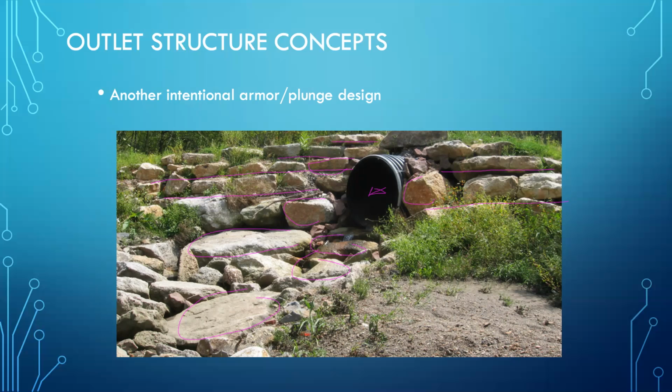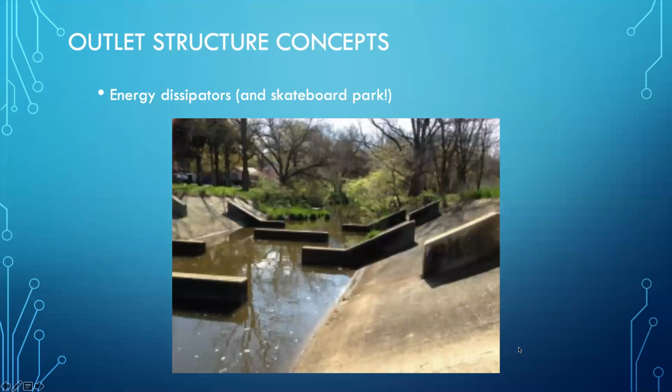So all these large stones were placed there on purpose, and the purpose is clearly, when this pipe is flowing at relatively high flow, there's going to be pretty substantial velocity, to protect the underlying substrate, which we can see here on the right of the picture is pretty fine, clearly erodible material. And then when nothing else works, we resort to our friend concrete.